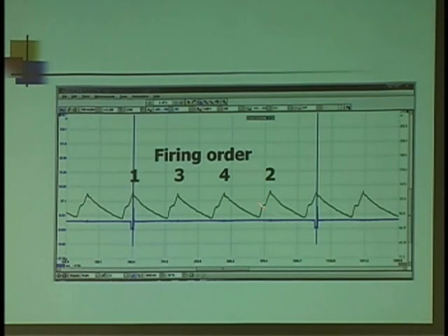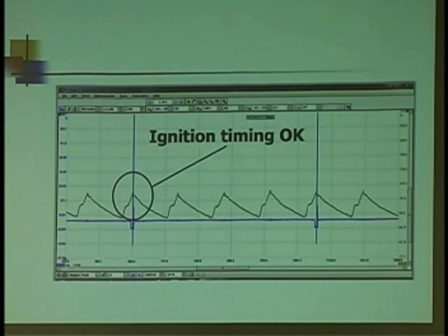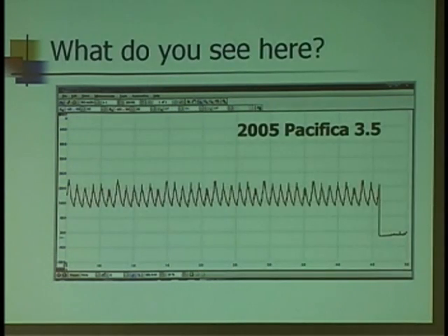Just say that the hump on number 2 was low. Now I know exactly which one to go for. Maybe I don't have to rip the plenum off and start checking the back bank. Maybe the problem's up in front. Ignition timing is indication that that's okay.